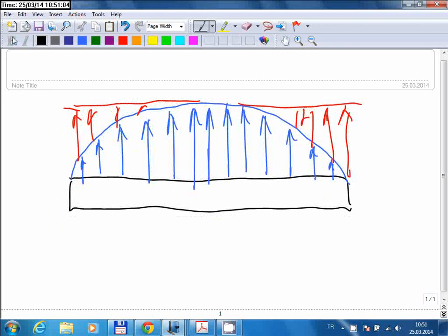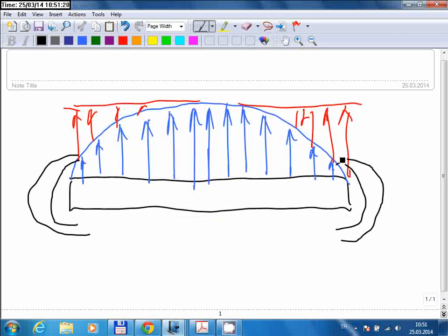So this is the front view of a wing, and the loss of lift at the wingtip and the increase in drag is due to these vortices, right? I won't be able to draw nicely with the mouse, but there are these vortices here, and if you can somehow reduce them, you cannot eliminate them completely, but if you can reduce them, you will get a big benefit in terms of aerodynamic performance. That means you will have more lift force and less drag force.